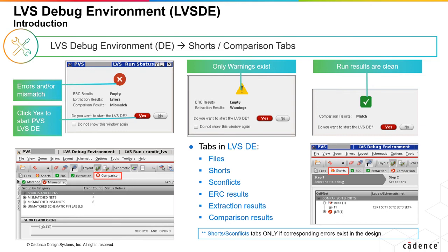When you click Apply or Submit in the PVS LVS Run submission form, the run is started and a Reports window appears. At the end of the run, the Reports window displays the LVS report of the run, which will be used for debugging of LVS errors. This .cls report file is organized into several sections such as PVS LVS comparison, cell match statistics, summary, etc.